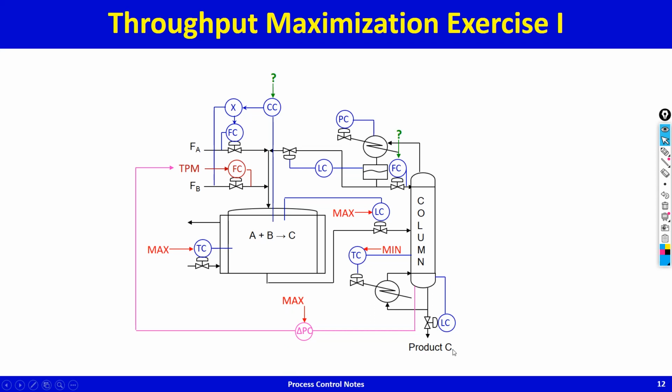You would like the delta P to be at max for maximum production rate, however the loop is long, dynamics is going to be very slow. Because the dynamics is slow, the control cannot be as tight, and therefore because of this long loop you will have a large back off, because the delta P max limit cannot be breached.